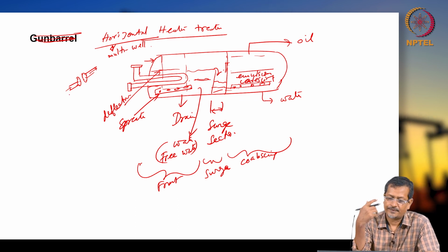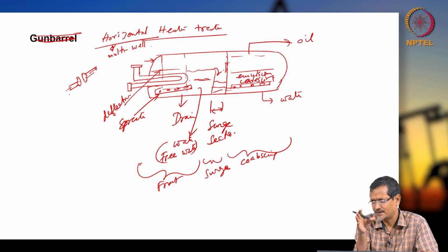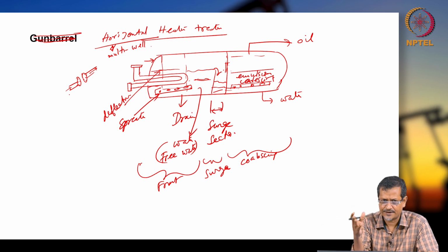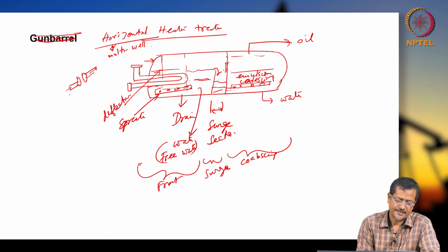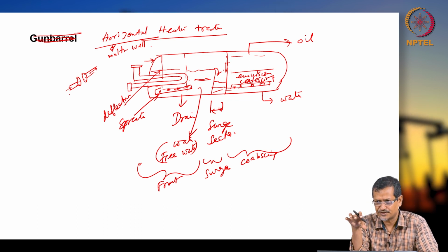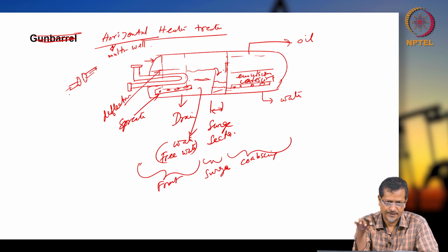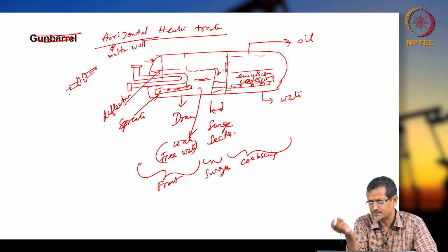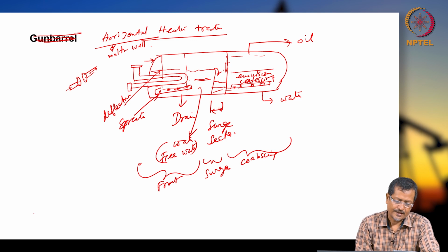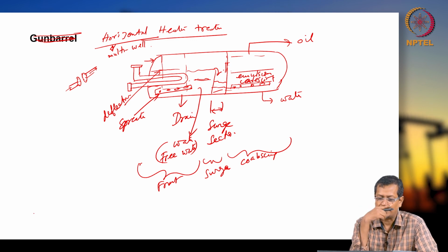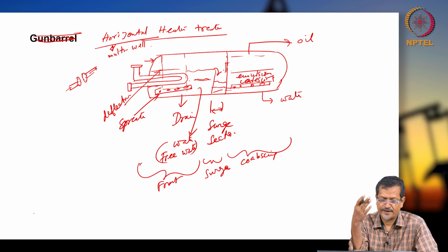But for a vertical separator, normally a single well gas, you can use a vertical heater treater. For low gas oil ratio, blanket gas may be provided so that you can maintain the internal pressure. If pressure is very low, in that case you can use gas from another source and maintain the pressure. Okay, a level safety low shutdown valve will be required, because level must be maintained in both cases,